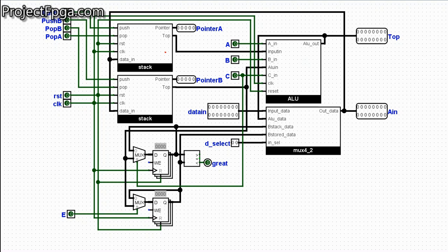So then again, let me show you how this greater than signal is being generated. That is how my algorithm works. First of all, a signal pops out the last 2 operators from the stack. The first one goes in here and is stored. The second one goes in here likewise. Depending on this signal E, which is used to turn on this register here, and immediately after it, this one comes on also. So whenever the signal E comes on, which is also coming from the control, this multiplexer stores the popped out data from the stack. Then the next signal stores here.